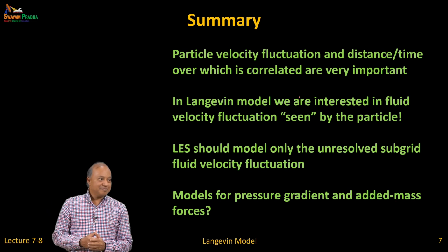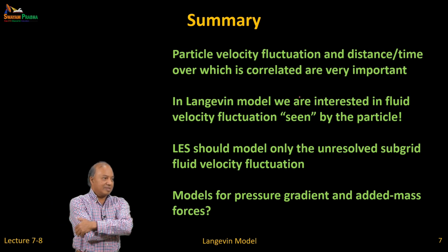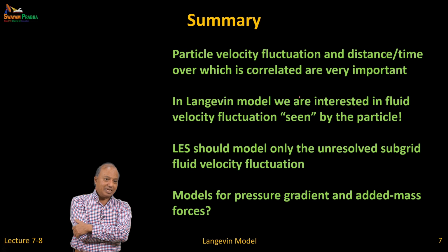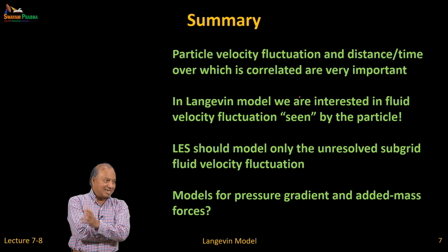Okay. So just to conclude, you put the scene in like extra quotes. So what is the significance of the fluid velocity seen by the particles? The fluid velocity seen by the particle is basically telling you what the turbulent eddies are asking the particle to do. The BBO equation tells you, tell me what the fluid velocity is and I will move the particle. Now we are missing some fluid velocity, we are not using the correct fluid velocity, so we are sort of faking it.